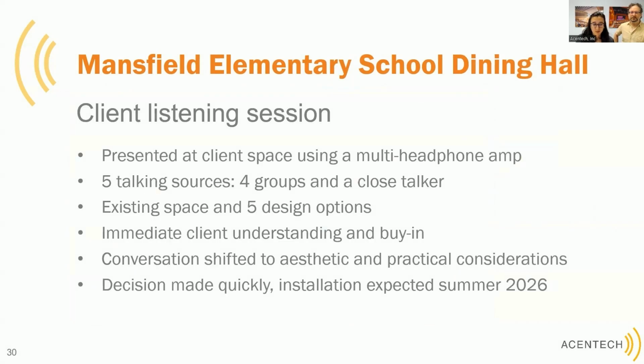So what was really amazing about this project was the culmination. We sat down with several stakeholders on the client side in the client space and set up a multi-headphone amp and presented all of these options using impulse responses that we took out of our Treble models, and then convolved with some other anechoic audio that we had to rebuild the scenario of a busy lunchtime.